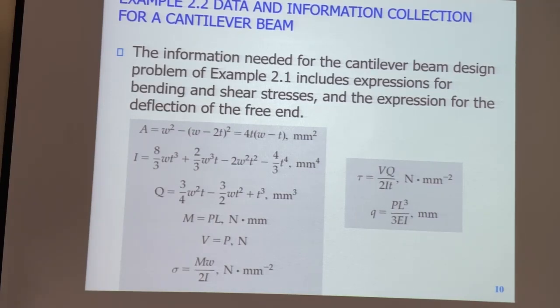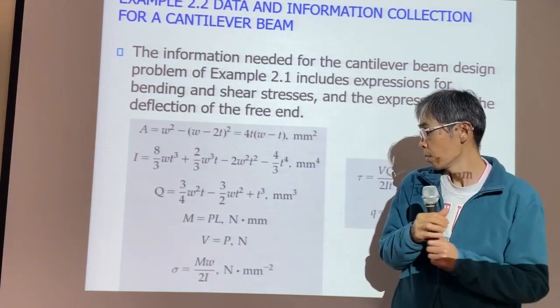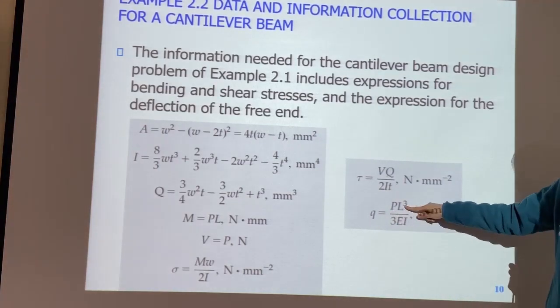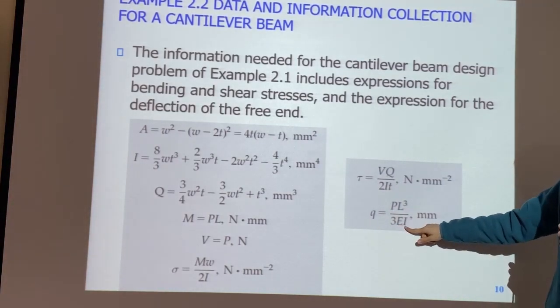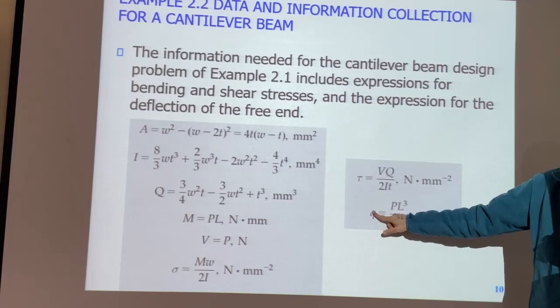Yes, see, we need the equation for the deflection. Load P, length L, Young's modulus E, and this is the second moment of inertia. Using this equation, we can calculate the deflection.